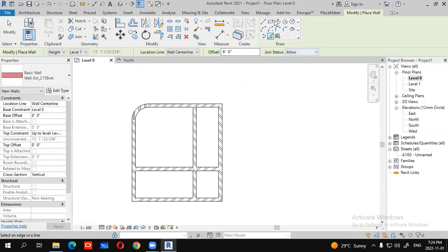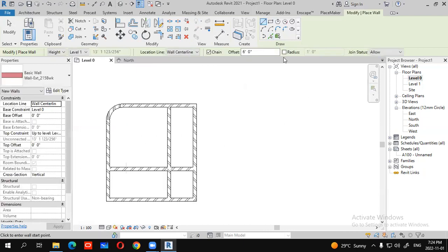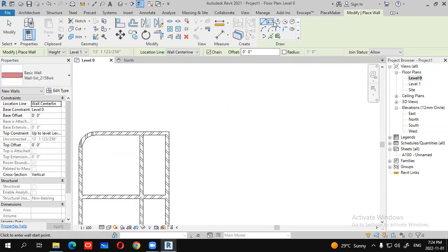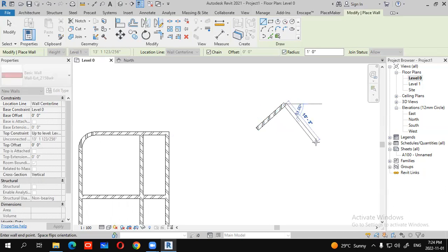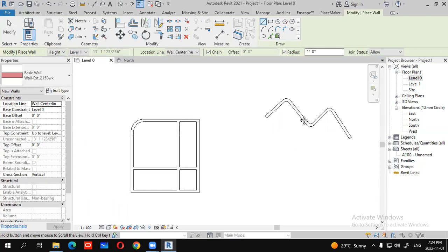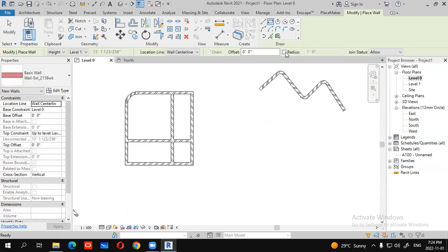Okay, next in the same way, here one more option called radius is showing. Okay, radius is a fillet radius for line and rectangle draw tools. For example, I took line and turned radius on. Then I'll create it in this way. So it automatically fillets at those corners there. So that is radius. Like I'll take rectangle. I turned radius on.